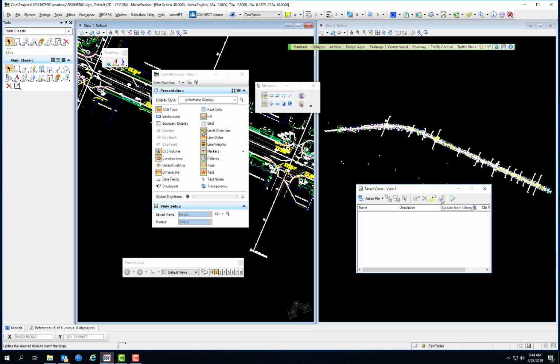What this does is it allows you to configure your workspace with a DGN library in the workspace configuration that contains saved views, so you can access those saved views regardless of what drawing you're working with. And the list filter button, which if on displays a filter row in the list box that allows for the defining of any column.